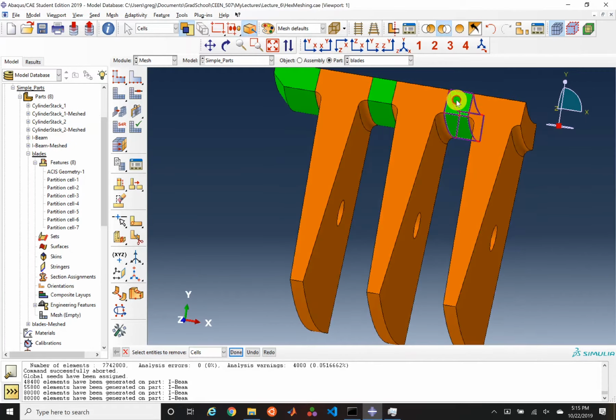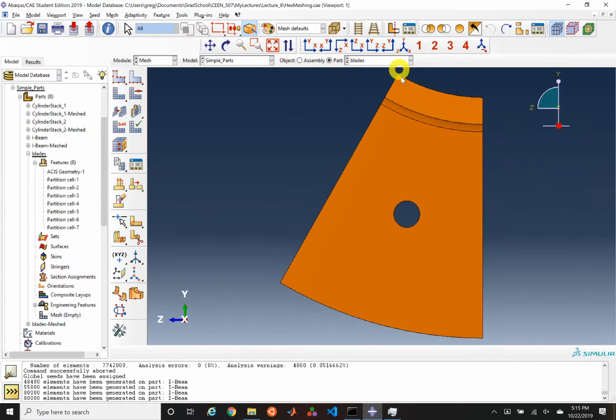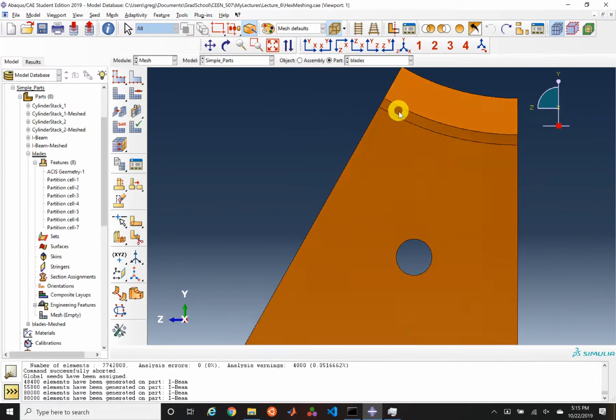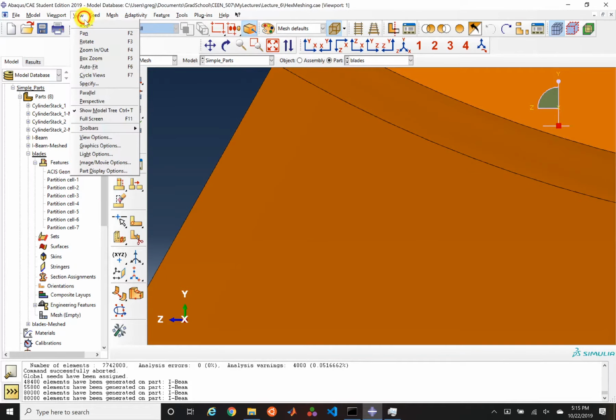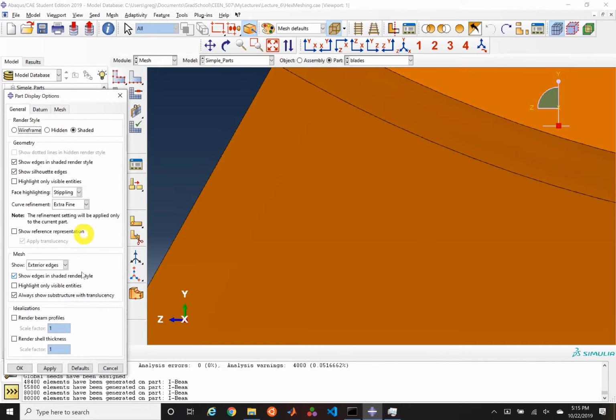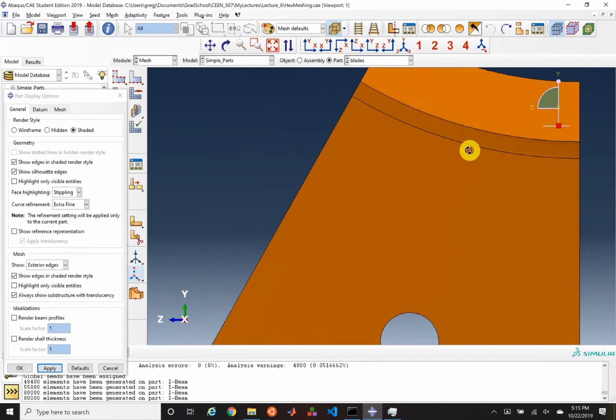But I'm also a bit curious about all of those fillets that we saw. So I'm going to go ahead and remove all these sections I can already mesh, and undo. I just want to see, could I possibly do something with these fillets? Maybe it's still a bit hard to see, but these fillets do line up with each other.